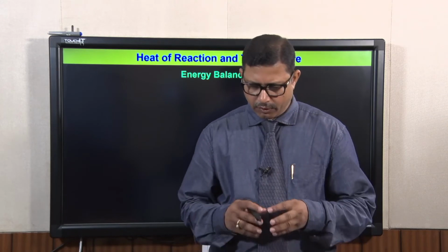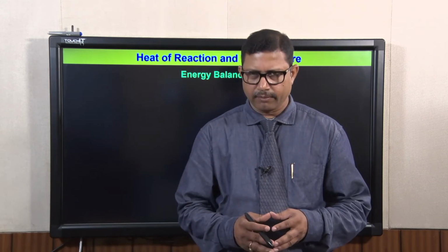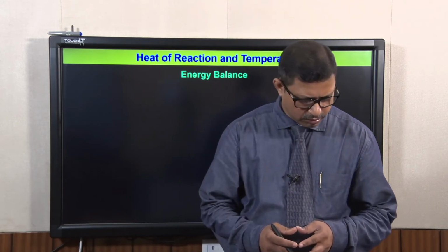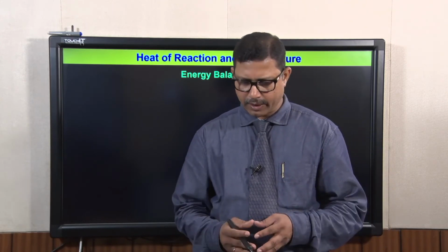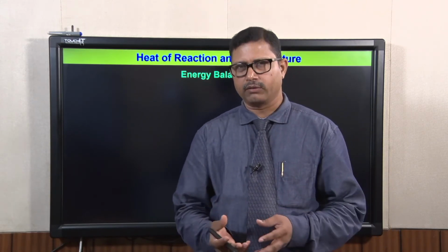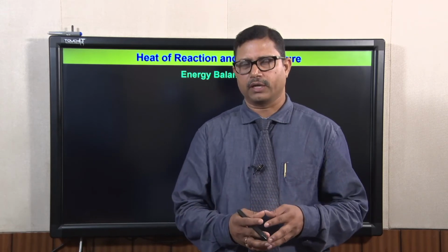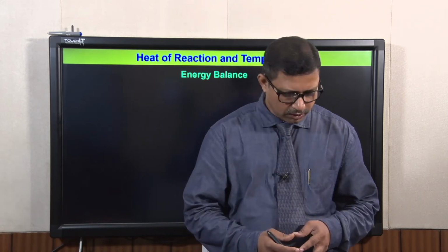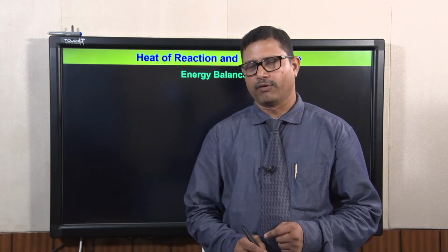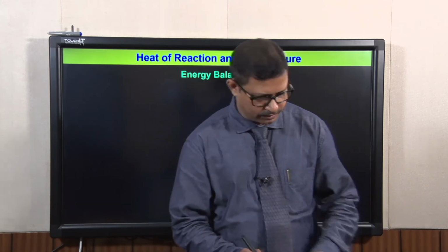Now, our first problem is to evaluate the heat of reaction, and knowing some value of heat of reaction at temperature T1, we need to calculate it at temperature T2. This can be done with the help of an energy balance equation.